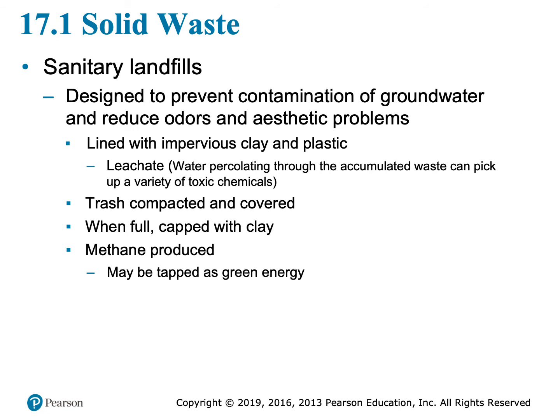So if we line the landfill with impervious clay and plastic, that leachate cannot get through. The trash will be compacted and covered. When it's full, it's capped with clay, and usually then grass or a park or trees are built on top of it. Methane is usually produced from the waste, and it could be a source of green energy later.